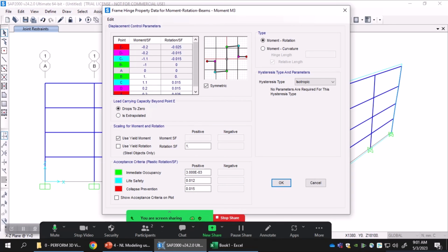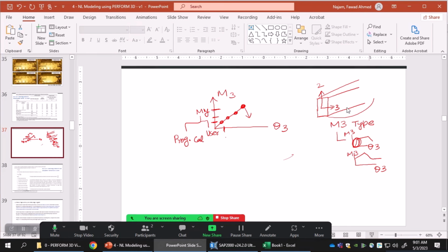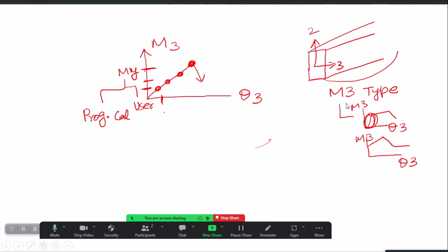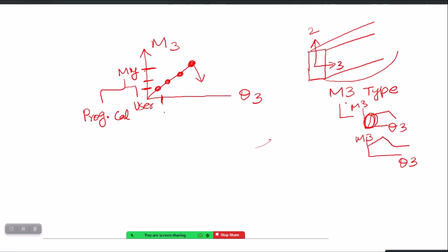Curvature is a deformation property for a cross section, right? So if I see this moment as an action applied to a cross section, the corresponding deformation will be curvature. But if I see it as a deformation applied to the full member, it will be the rotation. So let's assume that I am looking at a beam from the side or elevation view. You can see this is a side view before deformation, or before application of bending moment. But let's assume that it deforms like this after the application of bending moment.